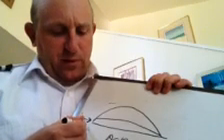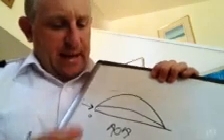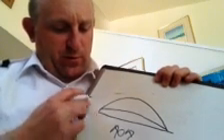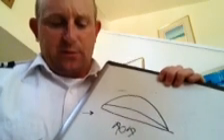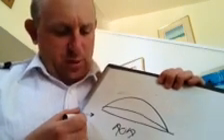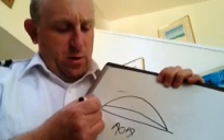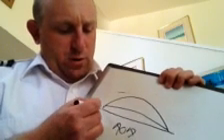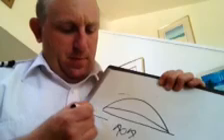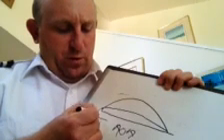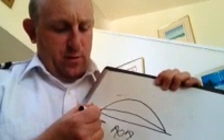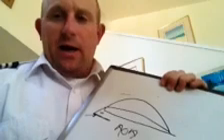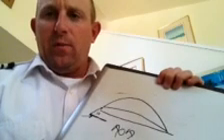So, for example, this would be a near 0 degree angle of attack, and if our relative wind was coming from down here, our relative wind also happens to be inverse to our flight path. If our relative wind comes down here, we're going to have an angle between the relative wind and the chord line, and that's called our angle of attack also. So this would be something maybe along the lines of 10 degrees. Higher angles of attack typically generate more lift.